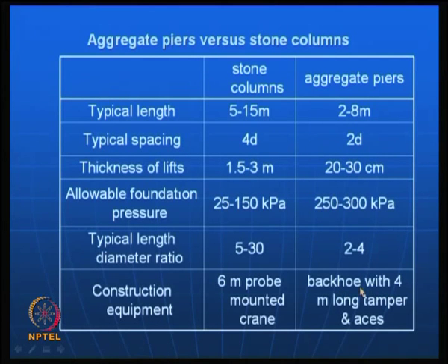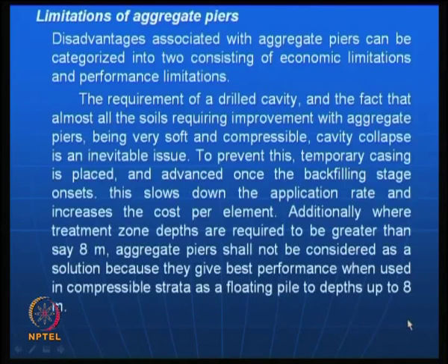That is called real time monitoring of structures, and people have been very effective, but then that is very expensive, but of course if the project is very big, one can afford it. In some small projects aggregate piers may be all right. So here the equipment that we need is about a backhoe with a 4 meter long tamper, some simple thing. So obviously the advantages are there, but then disadvantages are also there.